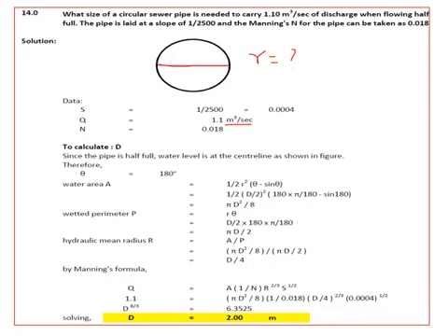Manning's n is given. Now when the pipe is running half full, the angle theta will become 180 degrees. So theta is taken as 180. If you want to use the formulas that are there, otherwise you can use area as pi r square for the circle, pi r square by 2, which comes to the same thing.